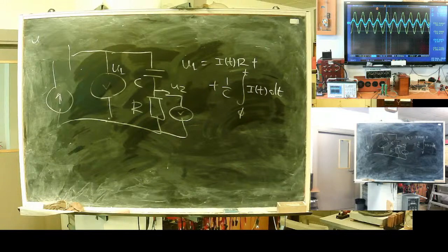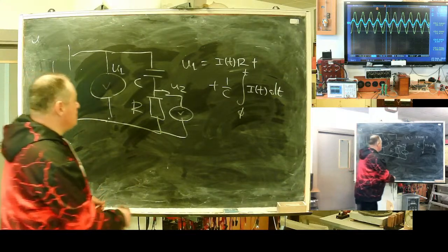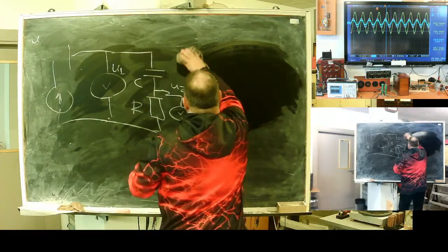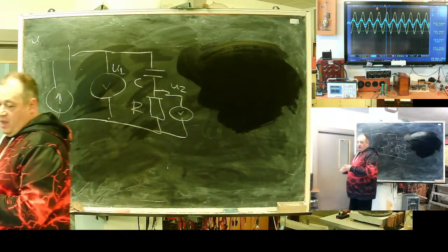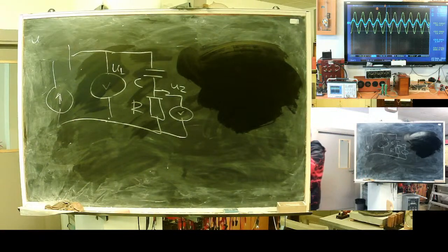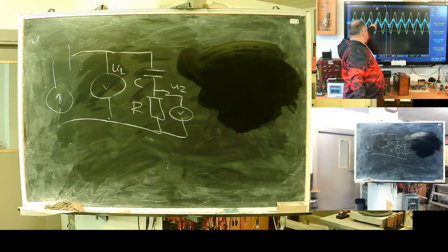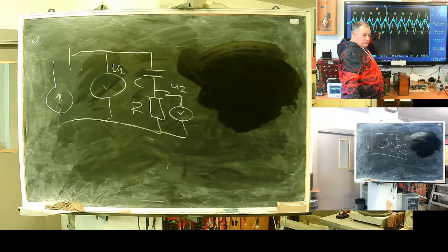This means that capacitance here acts like some kind of resistance, but we have a phase shift. To deal with it, the idea of complex or reactive resistance was introduced. Both coil and pure capacitance introduce a phase shift of 90 degrees, forward or backward. Voltage on the capacitor is delayed relative to current. In the case of a coil, it will be the opposite.